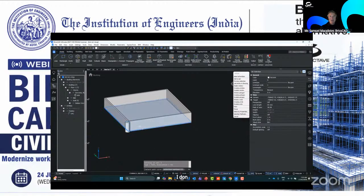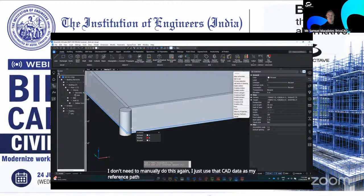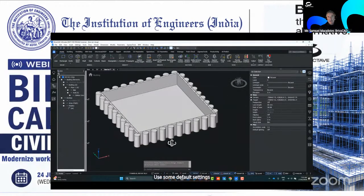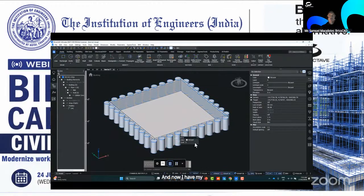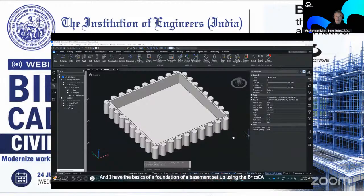I don't need to manually do this. Again, I just use that CAD data as my reference path, use some default settings, and now I have my piles arrayed around those walls, and I have the basics of a foundation of a basement set up using the BricsCAD BIM environment.